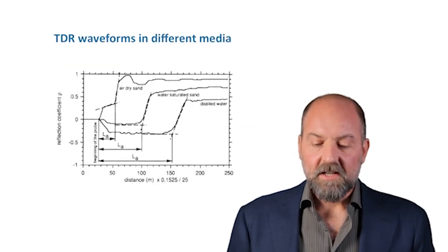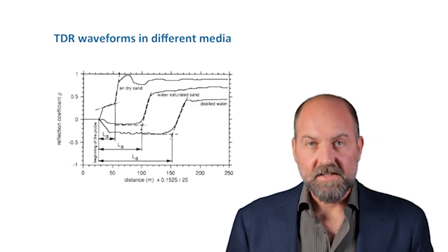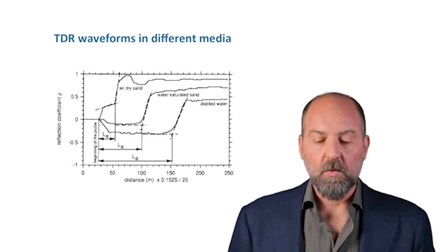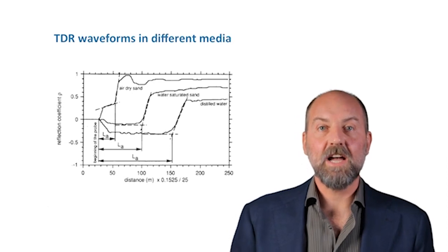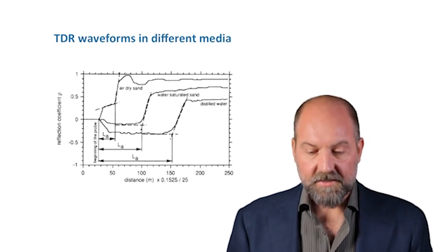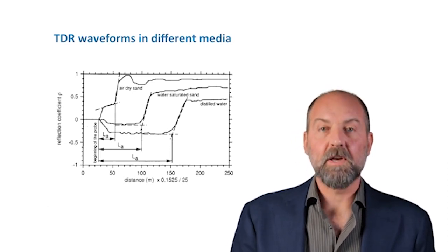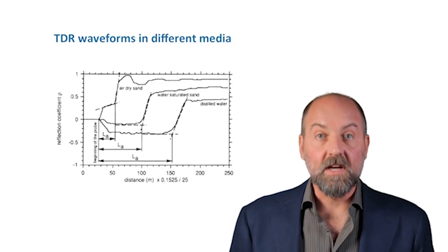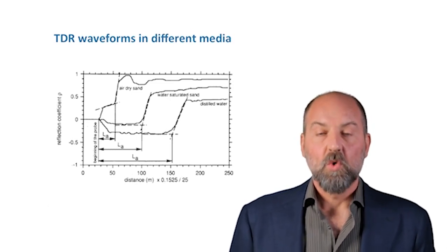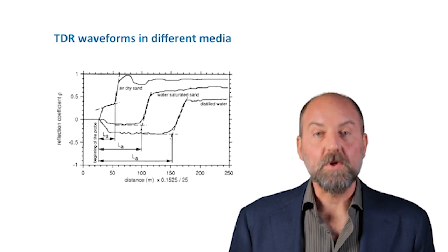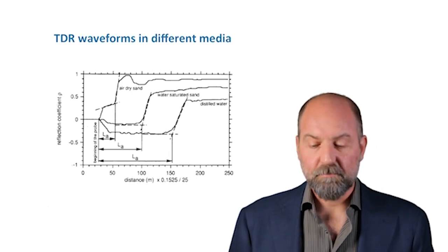And here you can see typical TDR signals obtained with systems at higher and higher water content. In particular, we compare air-dried sand with a fully saturated sand system.